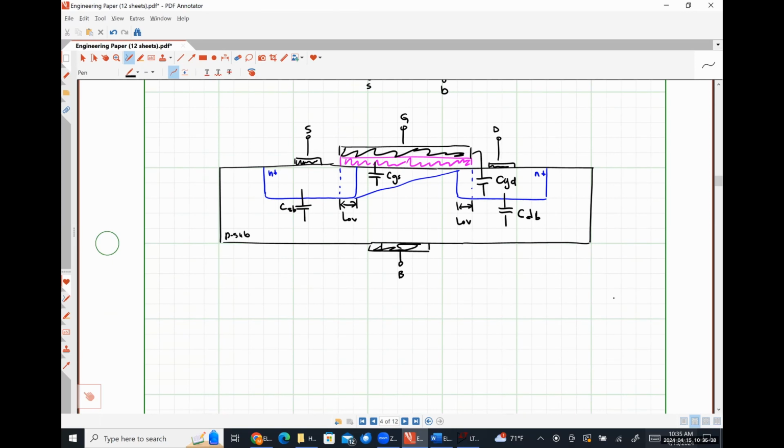So let's throw math at this. The gate source capacitance CGS arises because the polysilicon gate forms a parallel plate capacitor with the channel region, COX. When the channel is tapered and pinched off, the gate capacitance is approximately 2/3 WL times COX.